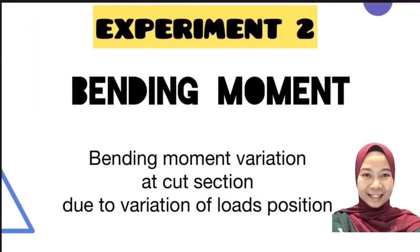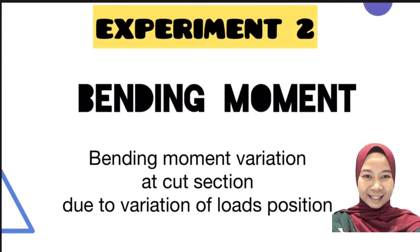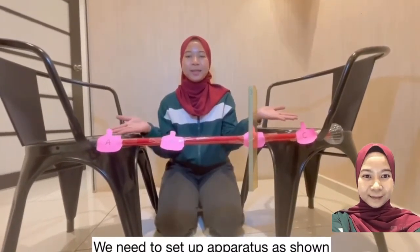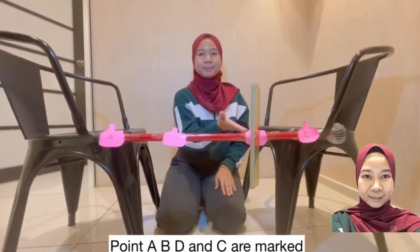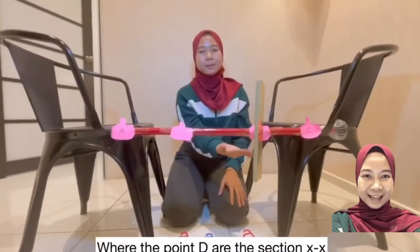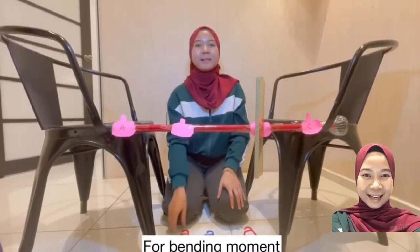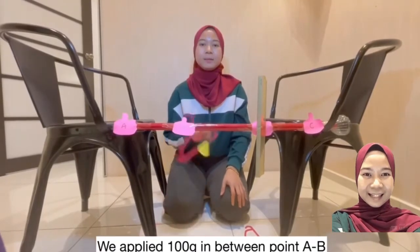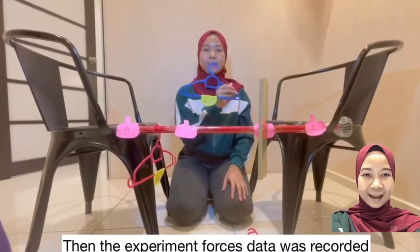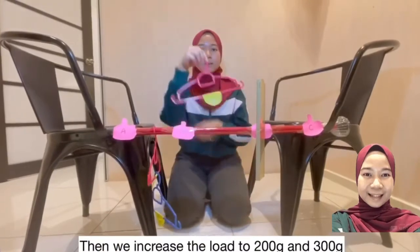Hi, I'm Shahida. To conduct the experiment on bending moment variation at the cut section due to variation of load position, first, we need to set up the apparatus as shown. Points A, B, D, and C are marked on the beam, where point D is the section XX to determine the bending moment. For bending moment, we apply 100 gram in between points A and B. Then the experimental force data was recorded. Then we increased the load to 200 gram and 300 gram.